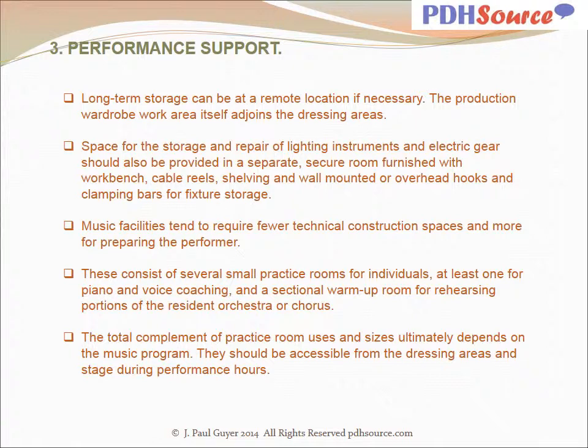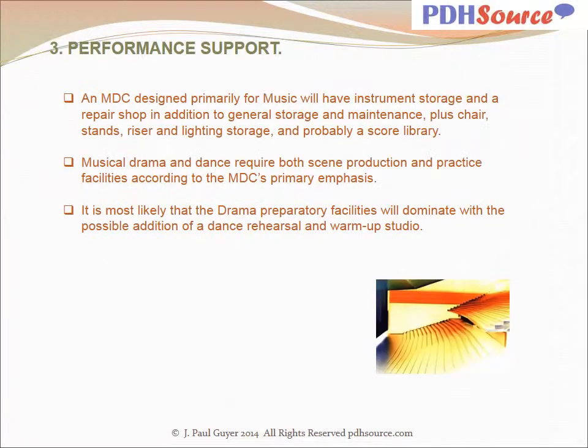Music facilities tend to require fewer technical construction spaces and more for preparing the performer. These consist of several small practice rooms for individuals, at least one for piano and voice coaching, and a sectional warm-up room for rehearsing portions of the resident orchestra or chorus. The total complement of practice room uses and sizes ultimately depends on the music program. They should be accessible from the dressing areas and stage during performance hours.